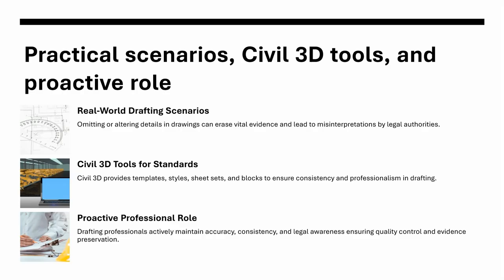Imagine you clean up a plat by straightening a riverbank that meanders irregularly. You might think you're improving the drawing from a legibility standpoint, but in fact, you're falsifying evidence. Imagine you use different line types than your colleagues. A judge may misinterpret the meaning of your symbols, and each of these violations is a hit against your required expectations.